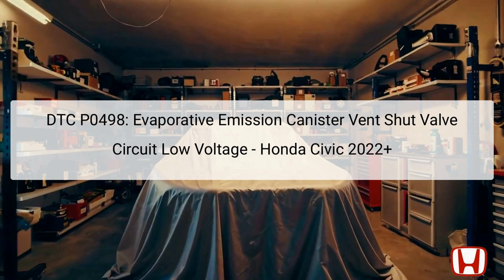This valve is located near the evap canister, typically under the vehicle near the rear wheel area on the driver's side. When the powertrain control module, PCM, sends an on signal to the valve but does not receive the expected on signal back, it determines that there is an issue and stores the DTC. The condition can hinder proper fuel vapor management, resulting in increased emissions and potential vehicle performance issues. Careful diagnostics are critical to accurately pinpoint the source of the fault.